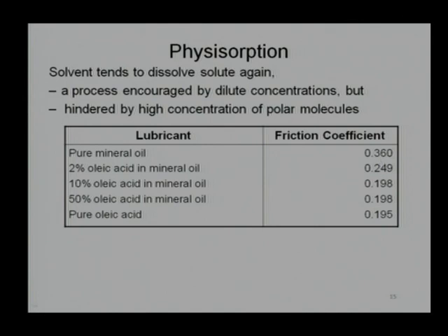roughly 0.25. Now, if we keep on increasing the fatty acid percentage from 2 to 10%, a 5 times increase, the coefficient of friction is not decreasing that substantially. It is going down from 0.25 to 0.2. If you keep on increasing from 10 to 50%, the coefficient of friction is not changing at all, it remains the same. And 100% oleic acid is very thick, difficult to pump, difficult to flow, and even in that case the coefficient of friction is not decreasing significantly, it is roughly 0.2.